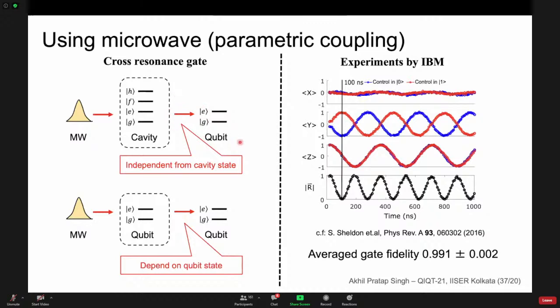So the disadvantage is you cannot tune the frequency of the qubit, but the advantage is that the noise is less, because if you want to change the frequency of your qubit, you have to put an extra flux line for each qubit, and that complicates your wiring and your crosstalk, and it is not a very favorable thing to do for a scalable quantum computer if you want to make thousands and 100,000s of qubits.